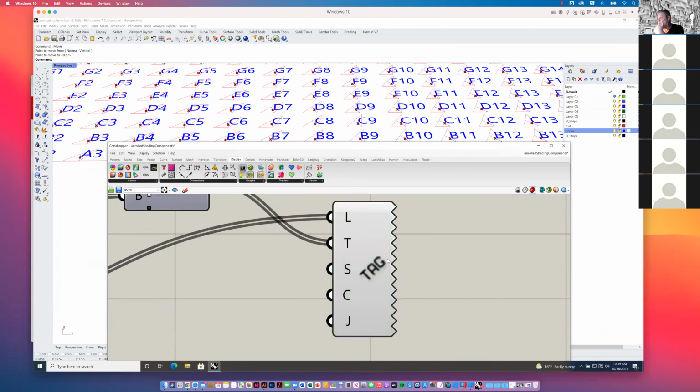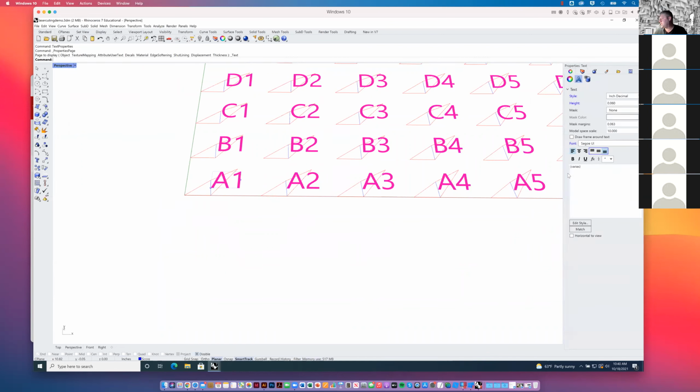All right. And so let me just look at these labels one last time and see what I can do with them. If I double click on them, does a box pop up? All right. Okay, and so I'm going to try to say SEL, cell, and then try to select all text together, cell text. All right. And let's see if I can change all their properties at the same time. No. Oh, come on. Here, let's see. Cell, text. I'll select them. Now I'm going to type in text properties. Let's see if I can bring up the text properties for these all at the same time. It did. Right over here in the properties, and now I can change their size.